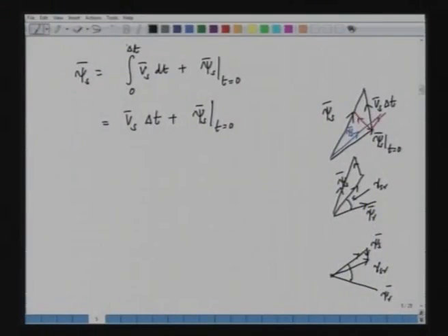Hence the torque of the machine is controlled directly, and the name is direct torque control. But to achieve this, we have to use a lookup table, which we will see subsequently. Now, let us see how the torque is controlled. To understand that in a little more detail, we will go back to our original 8 voltage vectors.